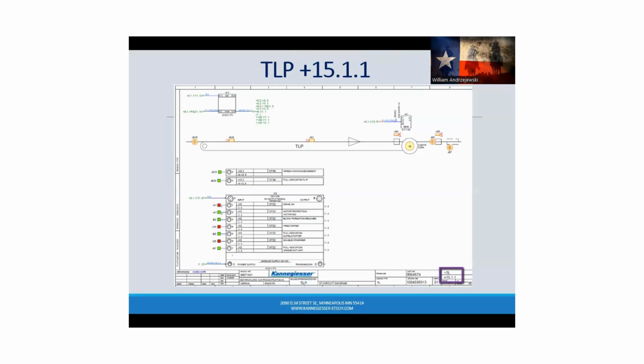Next thing we have common on all conveyors, we're going to have a full. We have to be able to know that if we get hangers backing all the way up to here, we need to tell the conveyor over here, stop, don't send any more. I'm full. So we're always going to have a full switch.